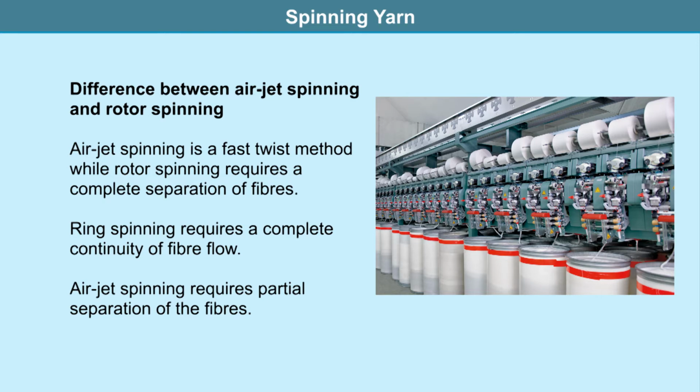When the bobbin is full, it is automatically removed and replaced with a new starter bobbin. Full bobbins are discharged onto an open conveyor at the center of the machine. Heat and air are exhausted through a filter unit at each end of the center conveyor area on the machine, producing an air wash which removes fine lint.